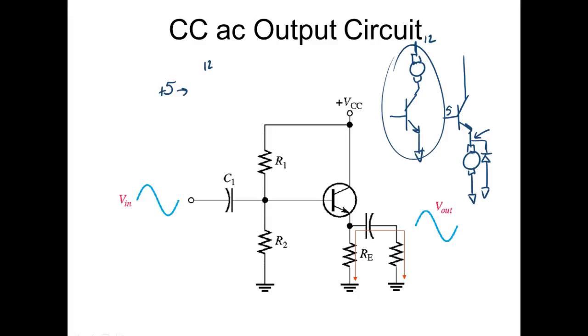If you take the power off a DC motor, it turns into a generator. So DC motors are pretty neat, especially shunt motors. We can either use them as motors or we can use them as generators. So we need to put that diode there to protect our transistor. We would put it up here, but we're going to reverse bias it. That way when the motor tries to generate, it'll turn it into a... Are you okay there?